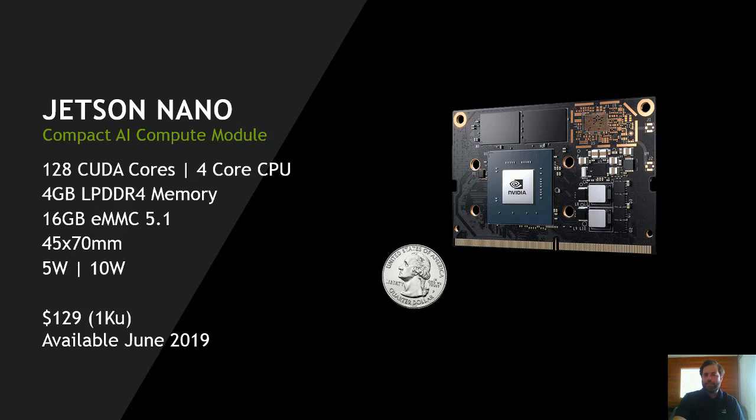The Jetson Nano compute module has the same processing capability that the dev kit does. It's a 128-core GPU, quad-core CPU, and 4 GB of RAM with the same core clock frequencies and performance. To accommodate embedded use cases, it has different storage than the dev kit. It has a 16 GB eMMC instead of the dev kit's removable SD card. It also has an extended warranty, and the production module is going to be available shortly in June with volume pricing of $129.